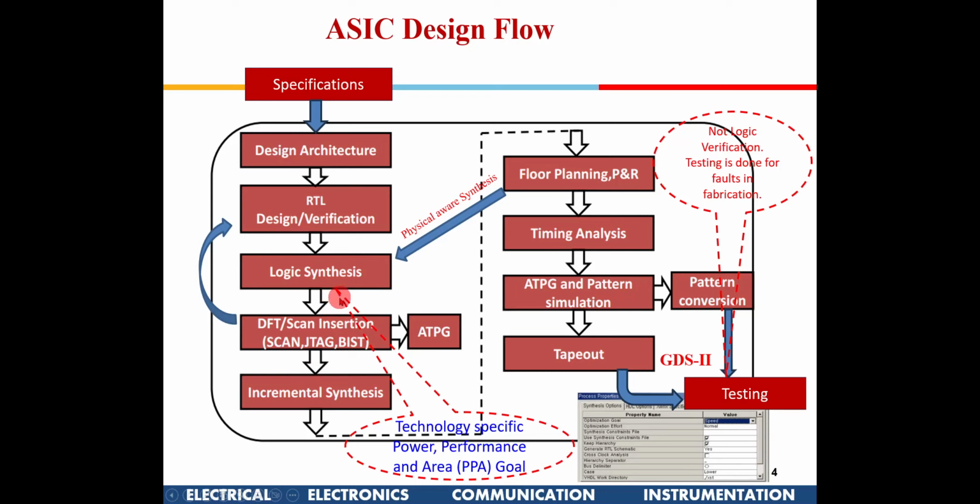Okay, so that kind of thing. Once that is synthesized, this particular RTL code may not have the provision for testing. So you need to include certain modules which will enable testing, right? Then you go back to the RTL design, do a verification again, because first, once you are done with the logic synthesis and have run a simulation, you are confident that this system works. Now you introduce the testing things also.